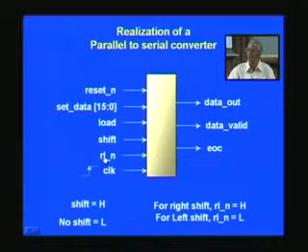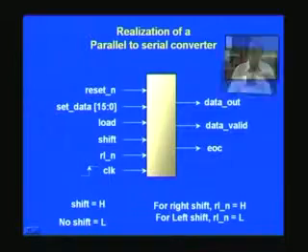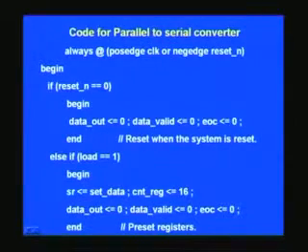L stands for left. I have put underscore n, as usual, the same notation we have followed earlier. So if it is low, it will be a left shift. Depending upon that and shift, we will take action accordingly. The positive edge of the clock is reckoned here once again, and we'll see how to code it. Once again, we use an always statement because all sequential circuits are represented by always with a positive edge of clock and so on.